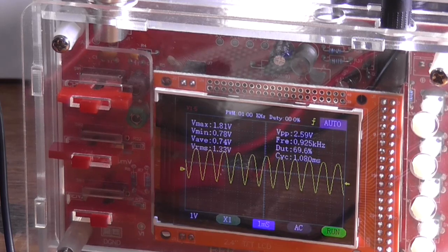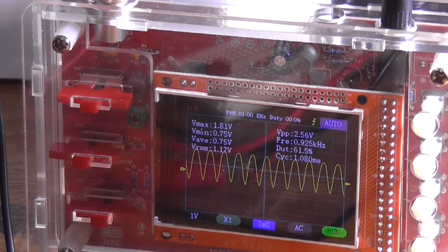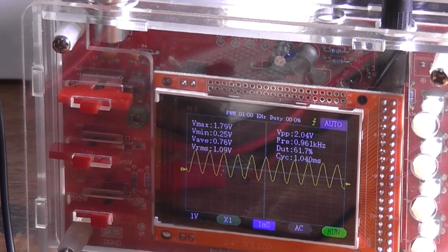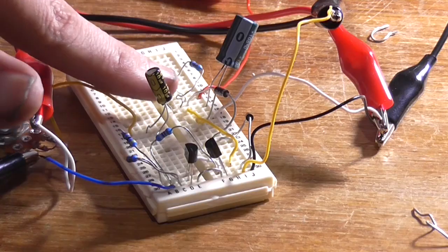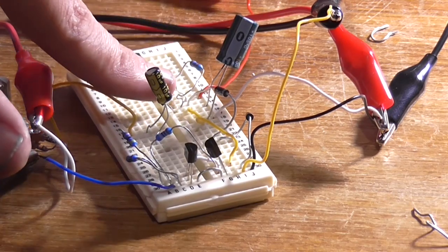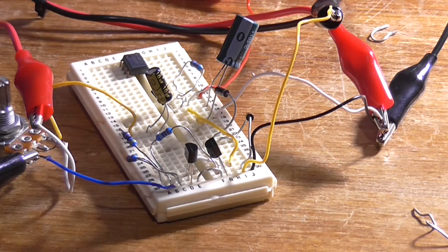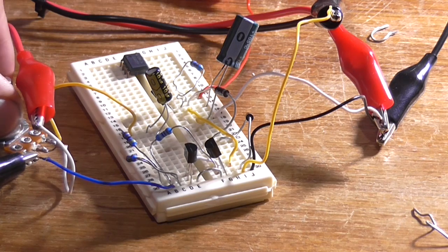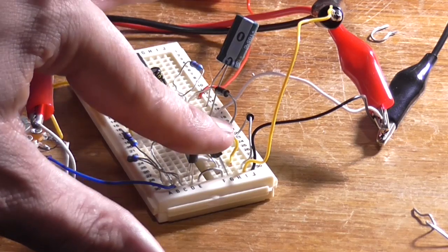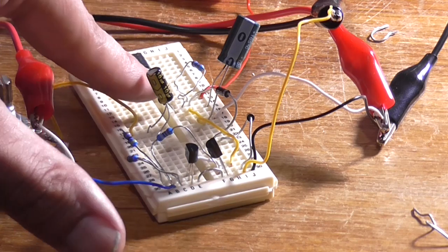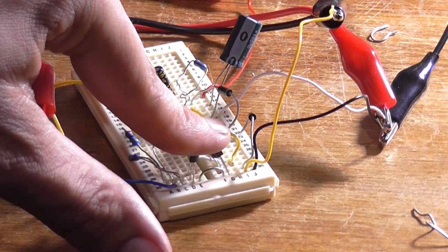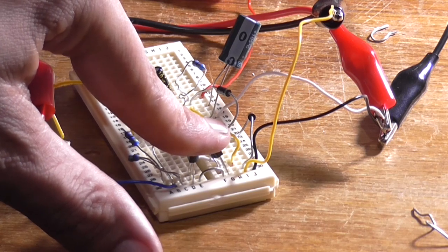Yeah, we're now getting 2.5 volts just before clipping, and the volume control's working a little less finicky now. These transistors are only getting mildly warm, whereas in the other configuration it was getting really hot. I'm getting closer to 3 volts peak to peak out. This is turning out to be actually a successful amplifier with some changes.